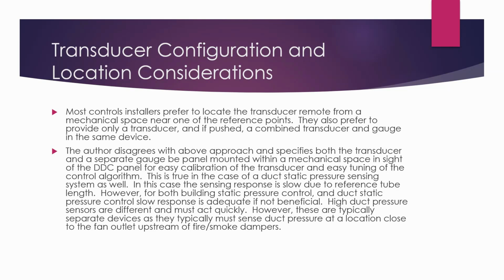So there is often a long length of tubing in this case, and I think that's fine personally. It averages out wind effect pressures, door effect pressures, and I haven't found any problem with having long lead lengths from the pressure sensors to the transducers.